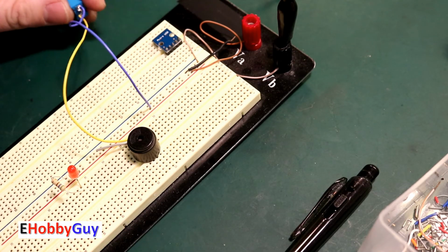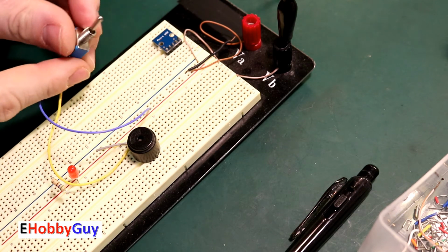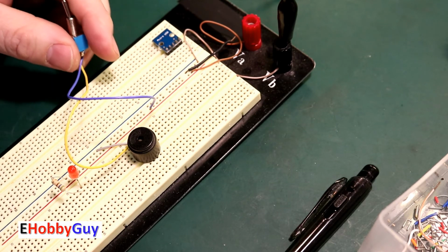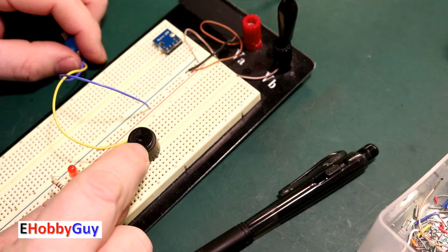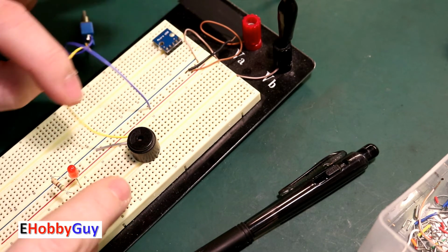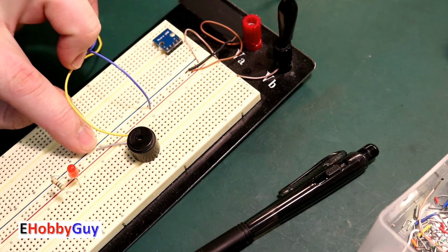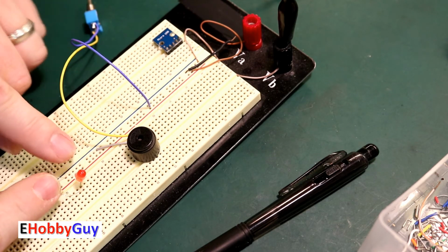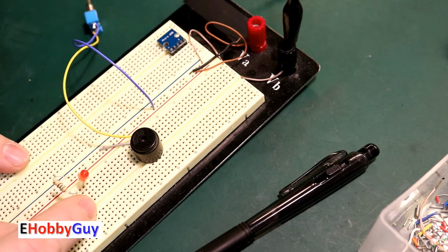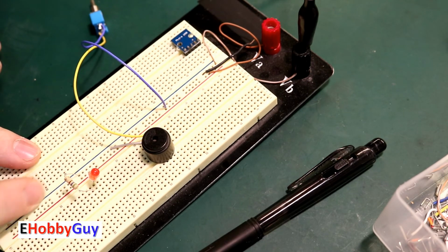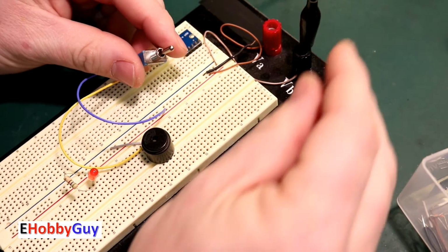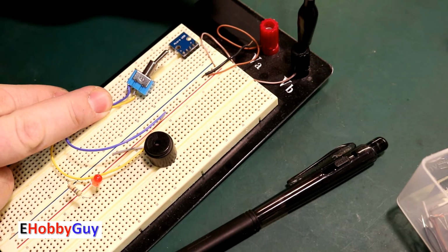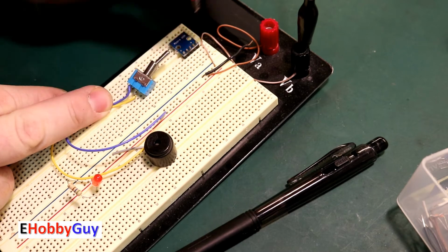So very simply here, I connected 2 wires to this switch. We're going from the positive rail, this red wire, through the switch into the positive of the 12 volt buzzer. Coming out of the negative of the buzzer is going right here to the negative rail. Here I have the resistor. Anode is connected to the positive, and the resistor is going to the cathode. Cathode is going to the negative rail right here. So I have the negative of my power supply hooked up here. I have 12 volts on my benchtop power supply. We'll see what happens. We should get the buzzer going and the LED coming on.